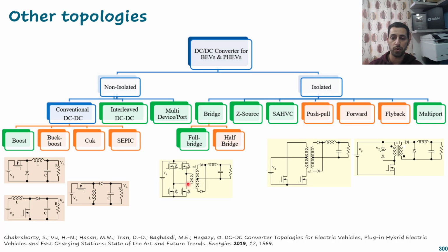And this is an example where at the primary side, we have a full bridge here. The full bridge means we have 4 switches, and they are like an inverter. If you remember the inverter, yes, it is making alternating current across that inductor, which is the primary side, and that will be transferred to the secondary side by stepping up or stepping down according to the ratio here, and you can rectify it and get the DC again. So DC, AC, DC.